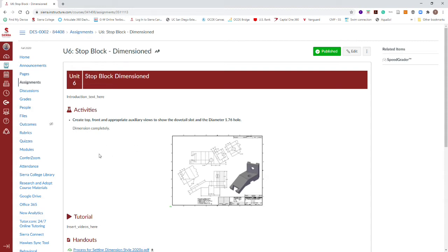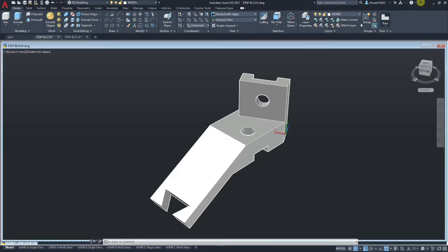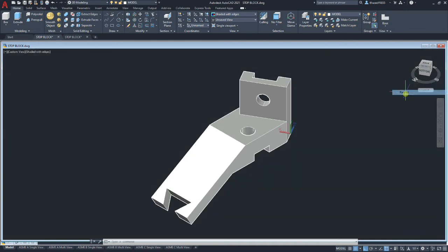So, okay, let's go to AutoCAD, and we have our model ready to go. And make sure you switch from perspective to parallel if it defaulted to that. Okay, now if we'd planned ahead, we could have named views ahead of time when we built the model. I did not do that. So I'm going to go ahead and go through the exercise of recreating those. So we're going to go to UCS.